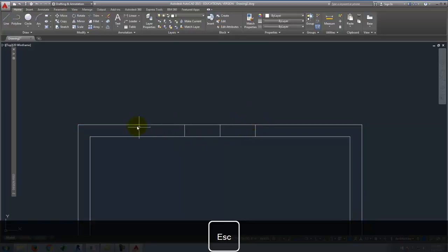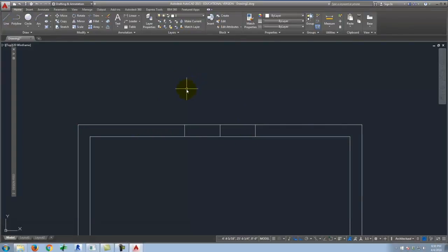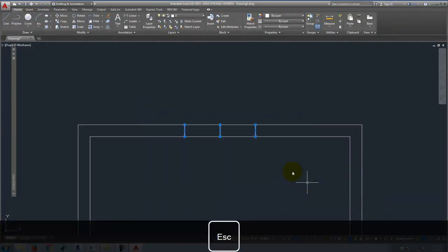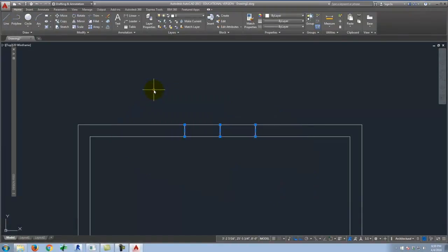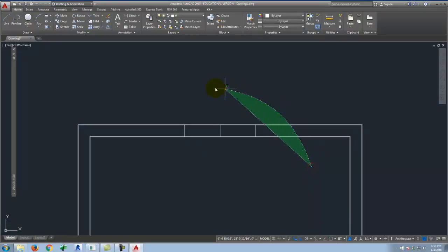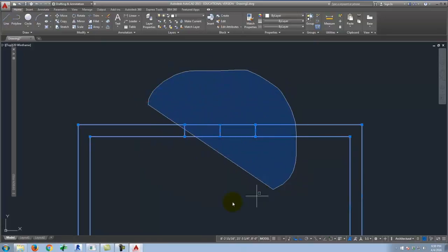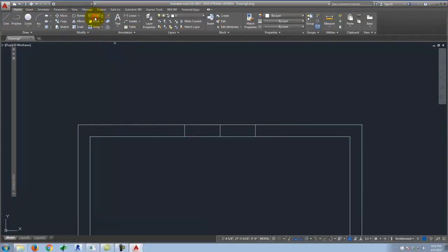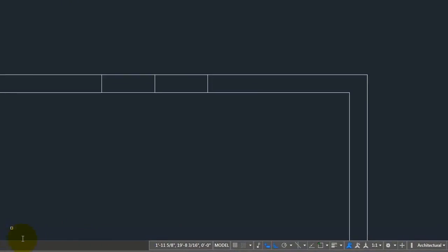The one other thing that I'll point out that some people have trouble with is, if I click and then I click, I get a rectangle selection. If I click and I hold, I can drag and create a free-form circular selection. The direction still matters. So if I go from right to left, it's green. If I go from left to right, it's blue. Make sense? Okay.